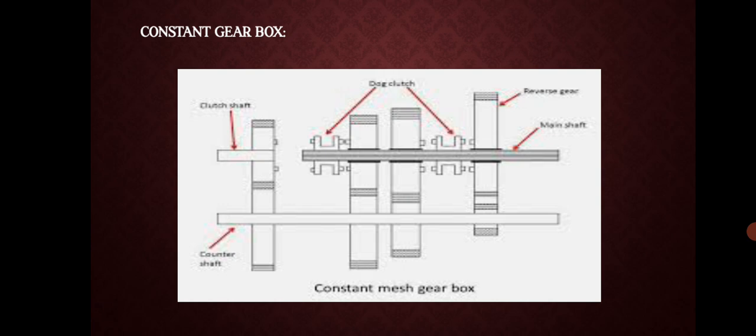With the exception of the helical gear drive to PTO and main counter shaft, the gears are of the spur type. All the gears being in the constant mesh and gear train connections being made by sliding coupling and connectors. The system incorporates a transmission type PTO. The main counter shaft is splined internally to accept the external splines of short PTO counter shaft.